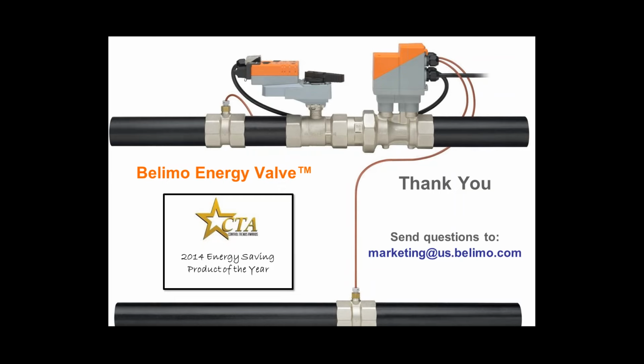Okay, and another question we have, how accurate is the data from the BTU meter? The Belimo Energy Valve's measuring equipment is rated at plus or minus 2% accuracy for temperature readings, flow readings, and BTU readings. So the short answer is that we're at plus or minus 2%.